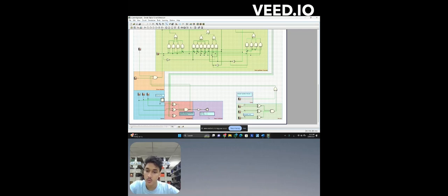One means that the door will open. If it's moving, that means it's working, working means it's one or high. So the output one will come to the NOT gate, which will convert it to zero. Zero means that the door is closed.